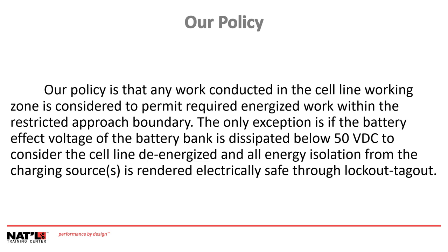What this basically says is that most of the time we will have to have an energized electrical work permit to work on a battery system or a cell line up within the cell line working zone.